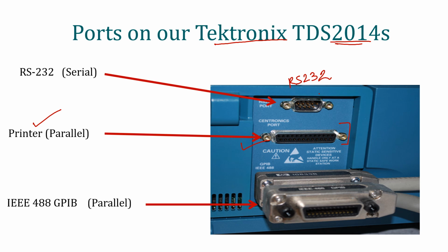Now this device is connected to a controller through this cable, and you can see whatever port was originally available at the instrument is now available at the extension of this cable connector, so that you can connect one more connector here and so on. So that is the beauty of these GPIB connectors: they connect with all the signals, send those signals through the wire, and also make each of the pins available on another female connector, so that we can connect one more connector on the same port. Okay.